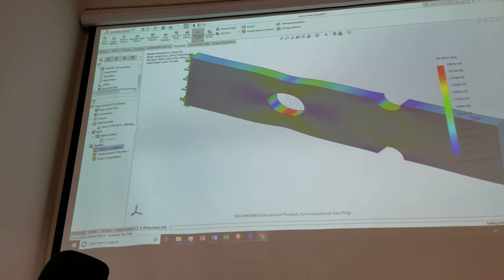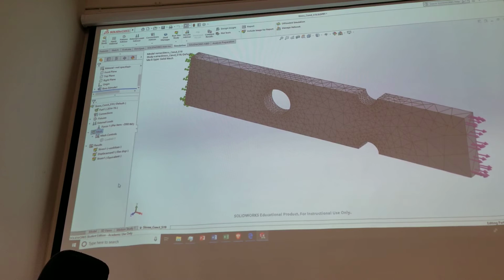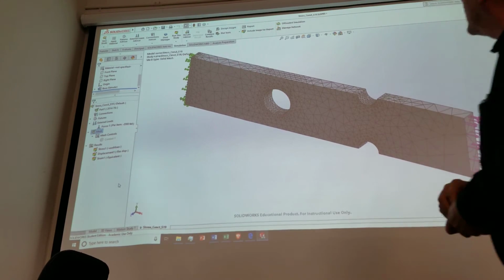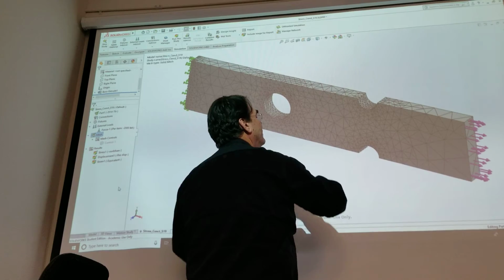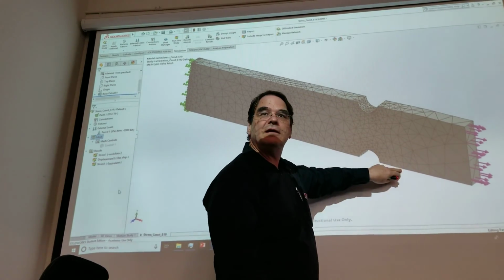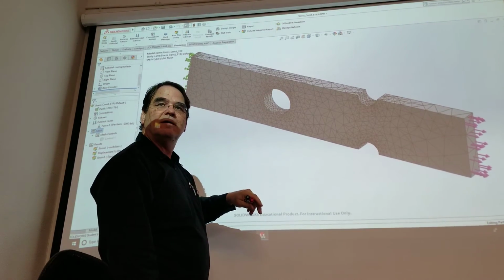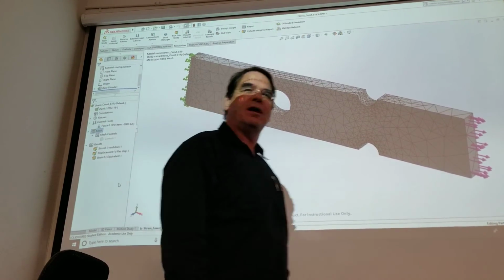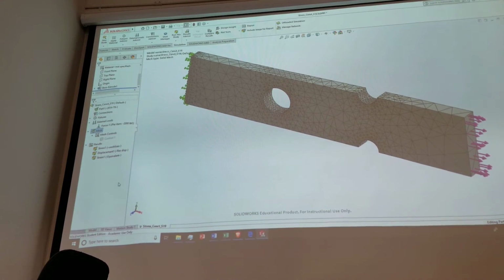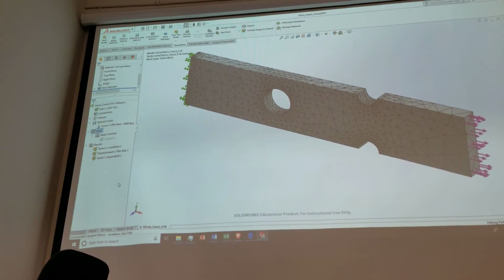And if I look at the mesh, now I'm going to show the mesh. This is my new mesh. You can see what it did. It started out all coarse and general, all uniform, spread out. That's what it started with. And what do we have? We got a whole bunch of stuff right over here, and right in here. And I've even got some stuff going on down here. I may not care about what's going on down here, but I do have weirdness from my boundary conditions. I get strangeness from the gradient, from the boundary conditions.